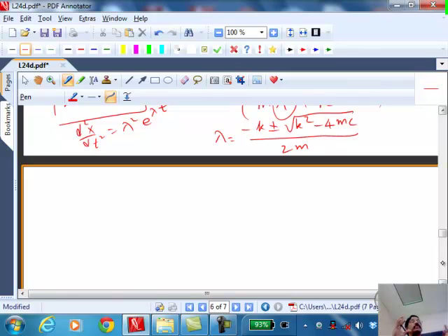And we saw in the last example that physical intuitive experiment where we said if I have two such systems mounted on the wall with a spring and dashpot, one with a steel ball, the other with a styrofoam ball. If I pull them and observe the oscillations, the steel ball will oscillate and go to 0. The styrofoam ball will just snap back, so its return would be very quick. The steel ball will take a longer time. And that information is all contained in here.